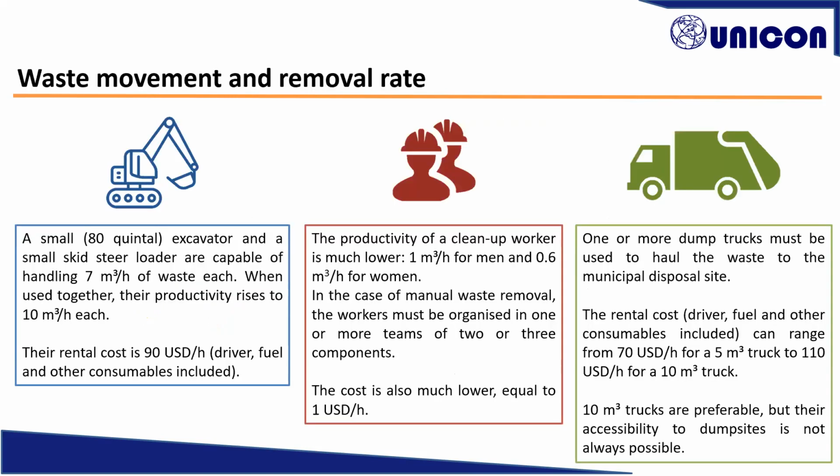There are different possibilities to remove waste from a dump site. There are, for instance, mechanical means that can be used. A small excavator and a small skid steer loader are able to handle 7 cubic meters per hour of waste each.